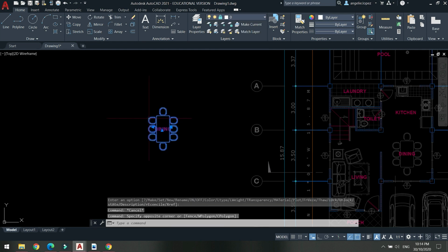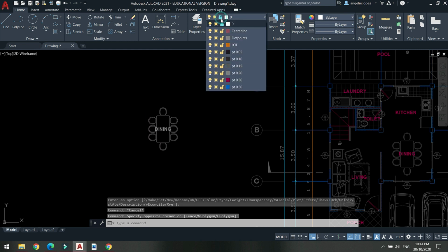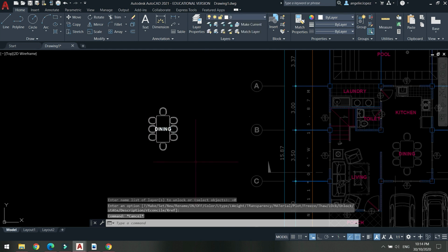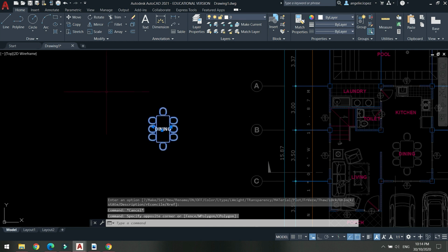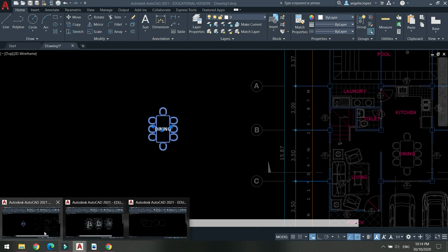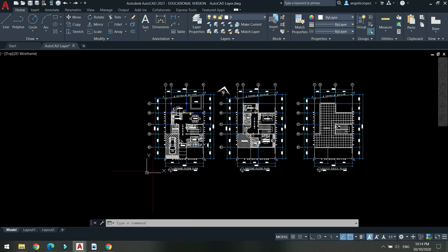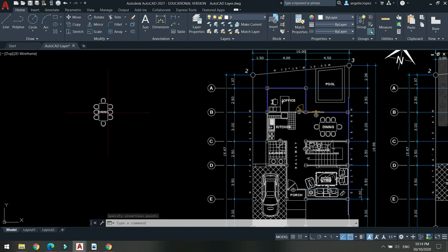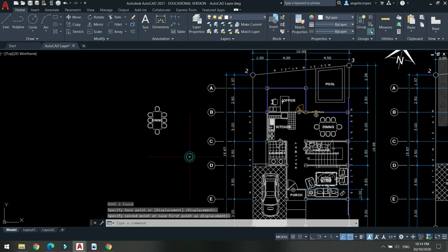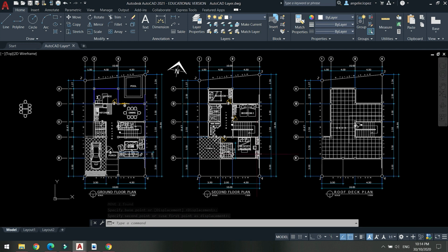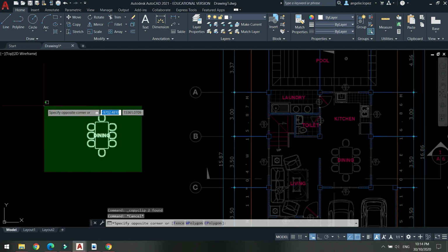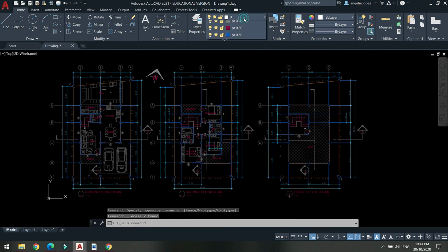I'm gonna set layer 0. Oh, I locked it. Alright. Now, it's white, so it's layer 0. That's the time I Control C and then go to the drawing and paste it. There, so no need to worry about my layers, it's still fine. So you have to maximize the layers and how to use them for us to have an efficient and categorized drawing. So that's it. Hope you have learnings on making layers. And actually, I am recommending pen assignment for the layering method.